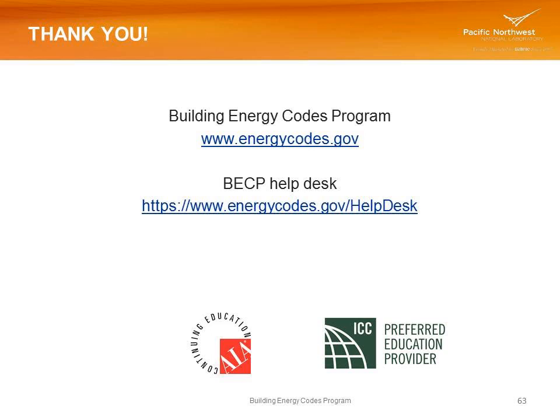Okay, so for ventilation code requirements, is it mandated to measure outside air into a building with an airflow measuring station continuously, or using carbon dioxide sensing? Yeah, we're talking a little bit about demand-controlled ventilation, and I didn't get into that today. There is not a requirement that the ventilation air be measured continuously. Some engineers may choose to take that route.